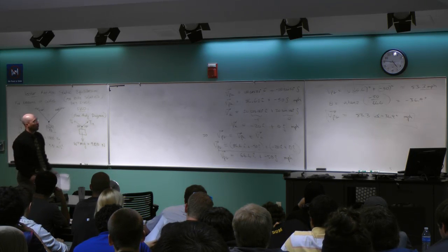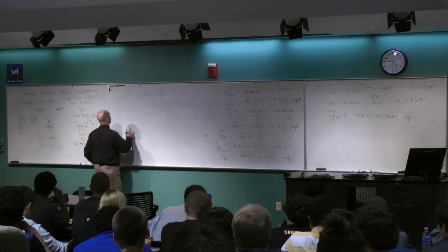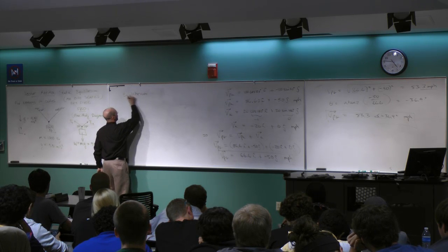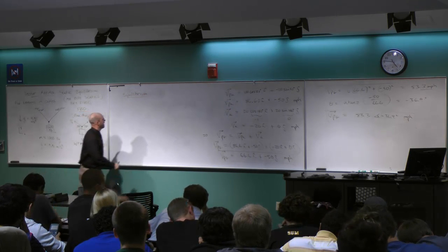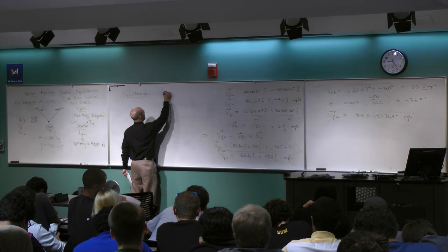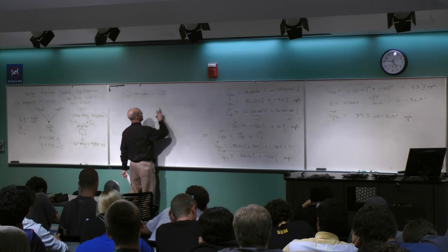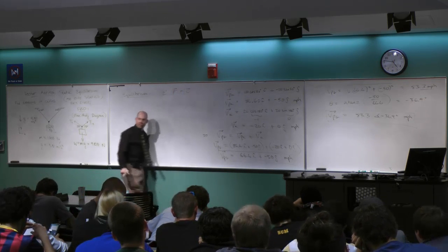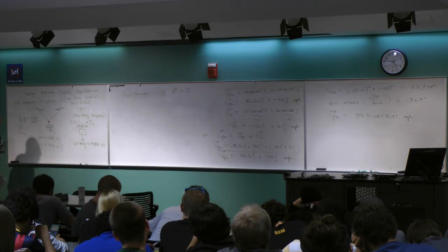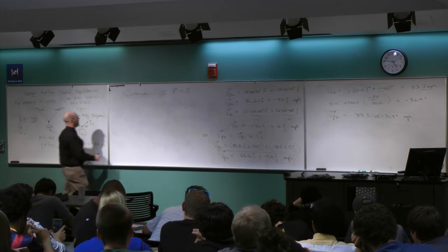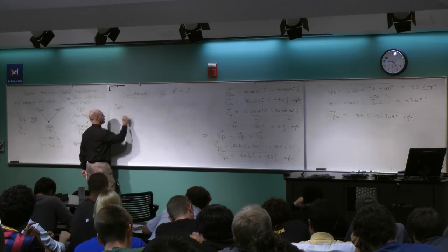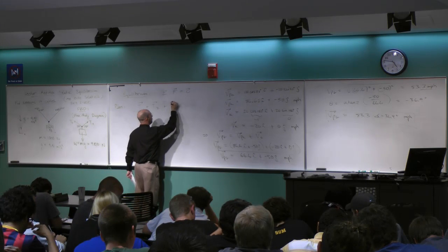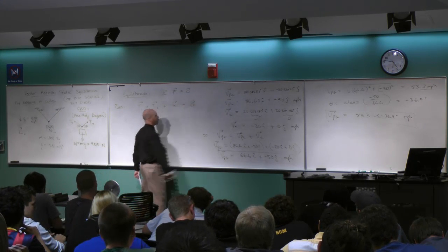All right, very good. So what we want to do is write this down. Equilibrium. It looks like we won't get this problem done, but we'll get it started for you guys and you can look at it. This says that when I add up the forces, the sum, this means summation sign, of all the forces is equal to 0. 0 as a vector, 0i plus 0j. So the plan here is I need to add these up. T1 plus T2 plus W, and I need to get 0. Okay?